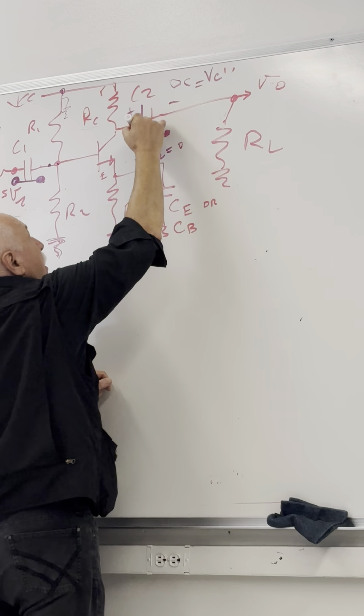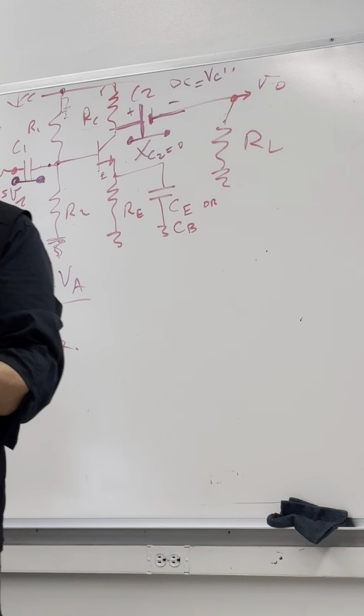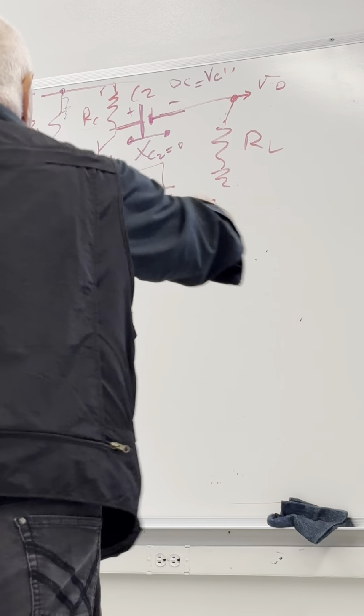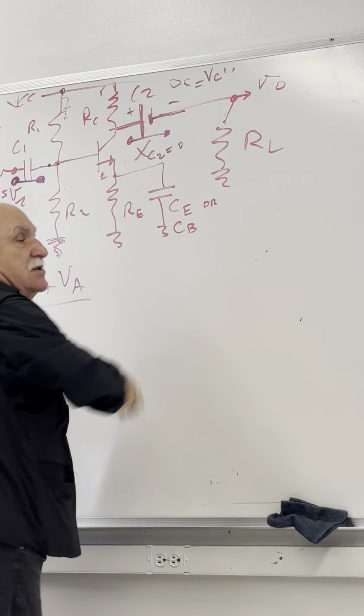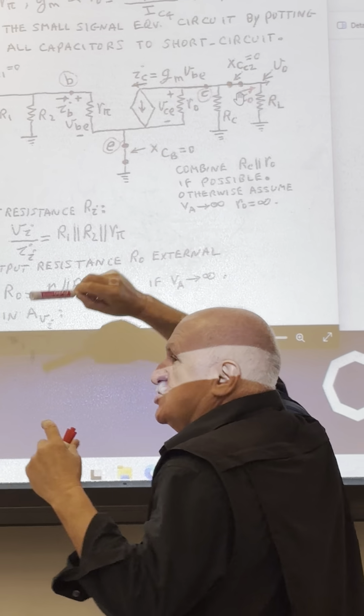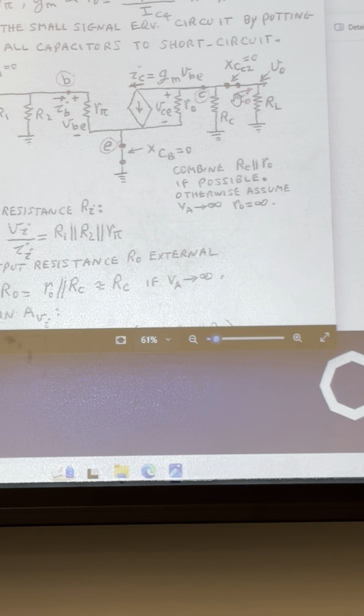Watch here. Because it is fully charged like a battery. And what did we do with the batteries? Didn't we short? That's why we shorted this battery in the model, you see? That's why we shorted that. Otherwise, it's a battery. Its value is VC, whatever the bias was. 8-volt bias there, it's like an 8-volt charged battery, already it's charged. So you put a short there, and finally RL to the ground from the other end of it.